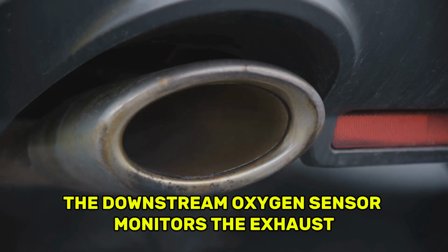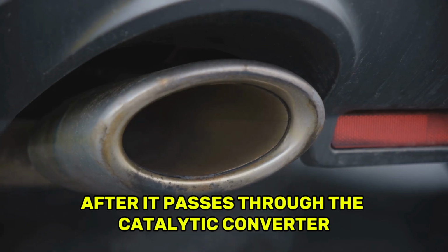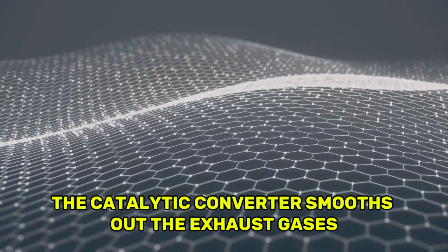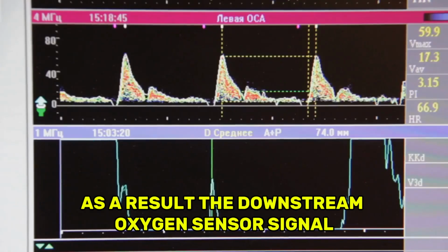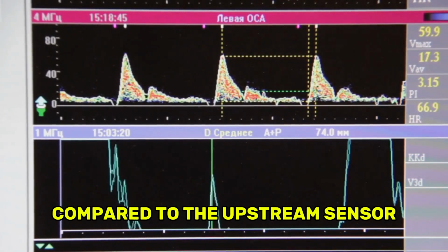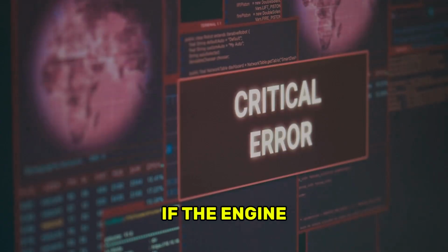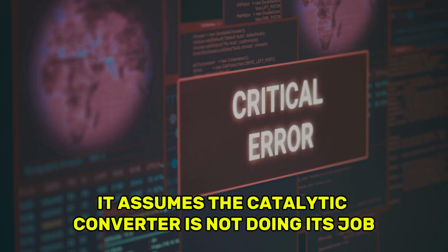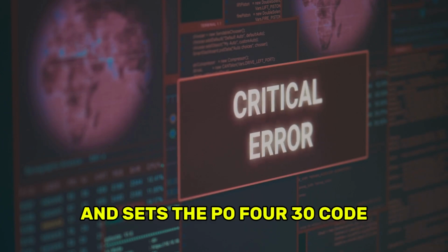The downstream oxygen sensor monitors the exhaust after it passes through the catalytic converter. In a properly functioning system, the catalytic converter smooths out the exhaust gases. As a result, the downstream oxygen sensor signal should remain relatively stable compared to the upstream sensor. If the engine computer sees that both sensors are behaving too similarly, it assumes the catalytic converter is not doing its job and sets the P0430 code.